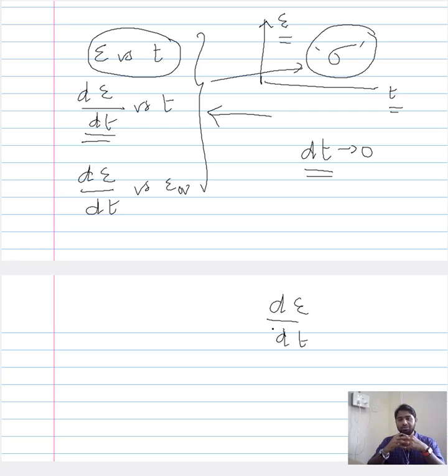Now when we assume that the strain rate is constant, we have to impose a sufficient amount of mechanical condition that would ensure this criterion. So we define our test in such a way that the strain rate should be constant all through the testing period. In order to achieve that, we have to impose sufficient load or mechanical condition that would ensure this criterion. Now we have seen that over a period of time this strain rate would vary.